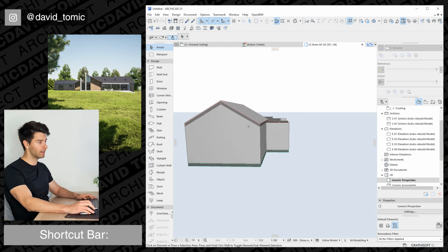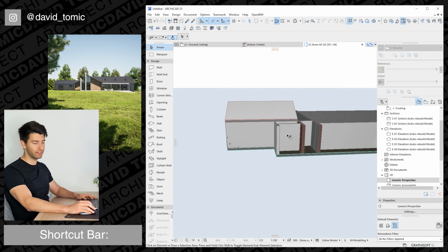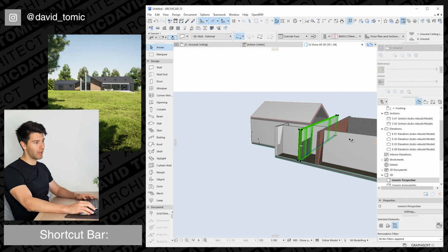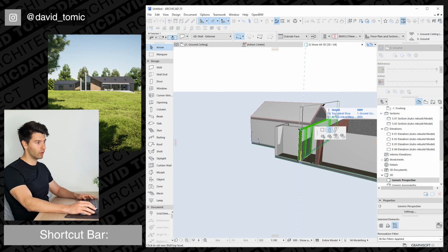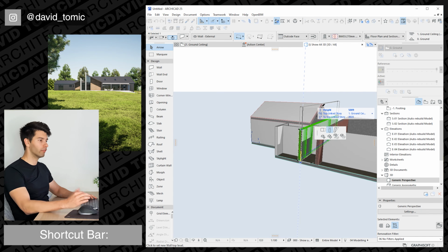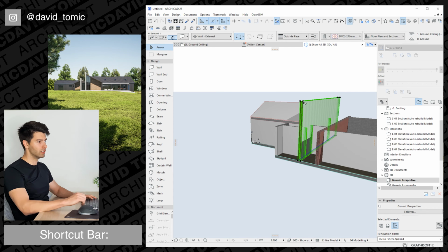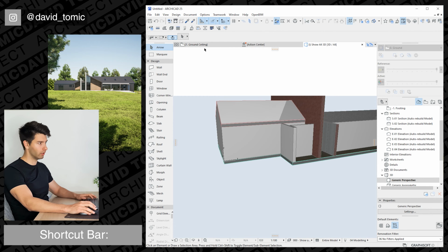I can close that palette, and there is our first gable roof on the left-hand side, which basically allows us now to emulate how tall this blade structure is going to be. So if I click on an external node, go to the top of that roof, I know I want that to be at least 500 millimeters higher than that. So let's type in 5500. It'll bump that wall just past that roof line.